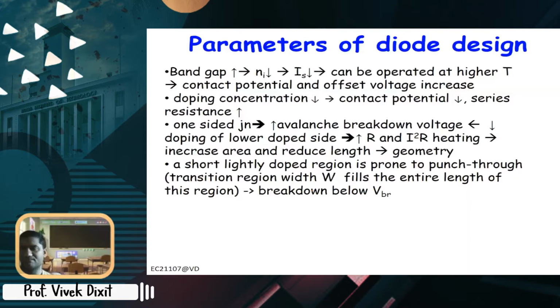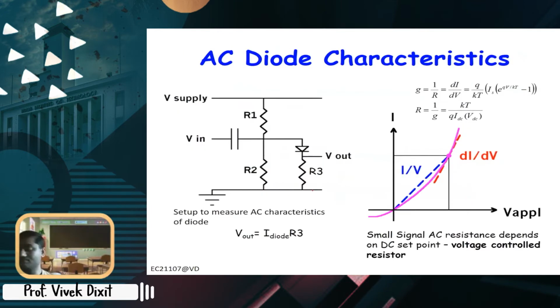Then let us begin our discussion on the small signal equivalent circuits. Generally, so far, when we discuss the diode, we say it has a dynamic resistance, right? Which is 1 by R dynamic equals di by dV. And of course, you can differentiate I, where I is equal to Is exponential qV by kT.